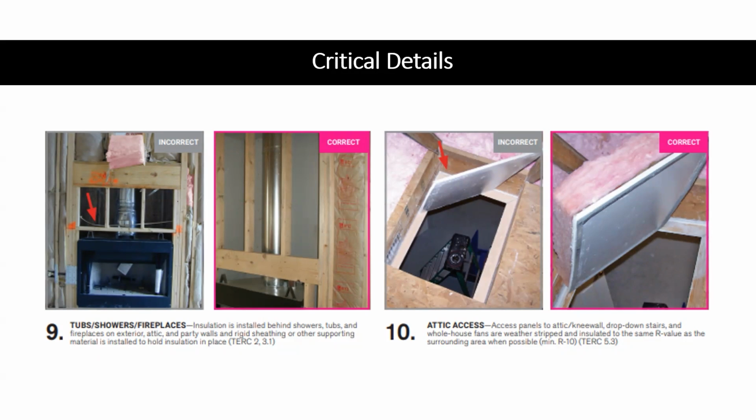So Matt actually says behind showers and tubs is one of the biggest struggles I have when doing insulation inspections. I agree, and I appreciate it. Matt was the one that actually emailed me about this and said, how do I enforce this? You really have only 2 options. Either they have to remove the tub enclosure and add another air barrier in front of it, or they can fully fill behind it with insulation. Now the tub is its air barrier, but they have to be in contact with the insulation. Otherwise, it's a misalignment, kind of like we're seeing in these pictures here.